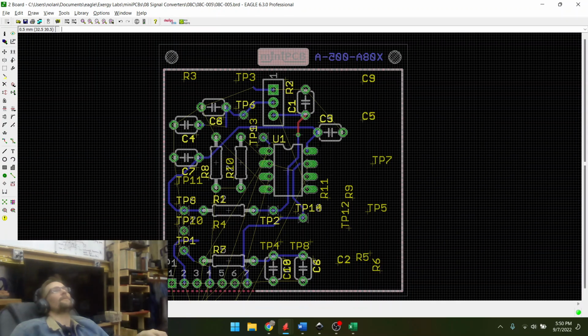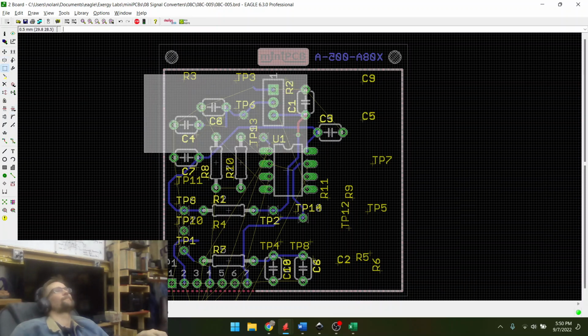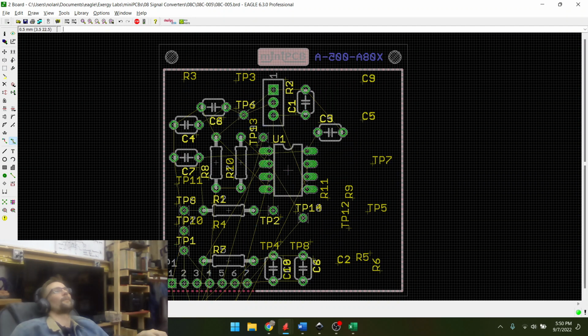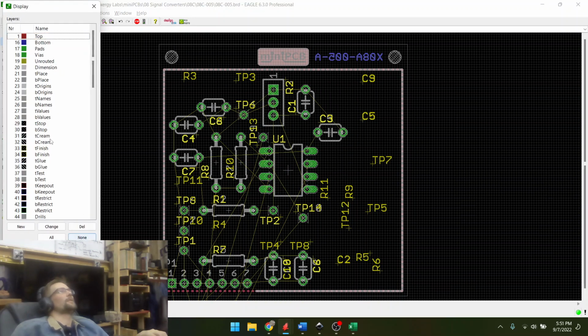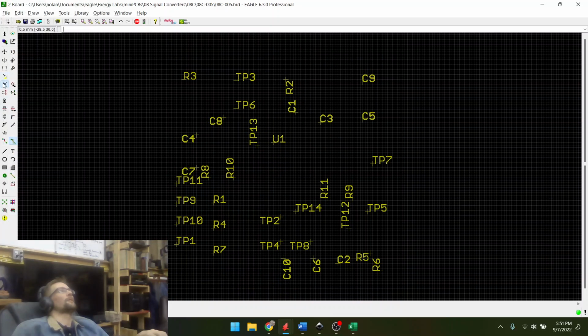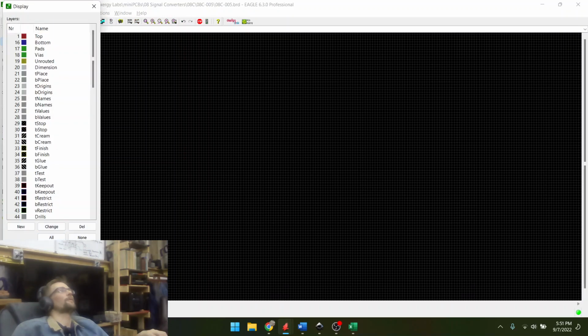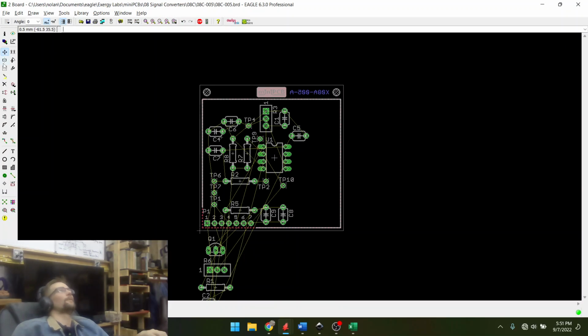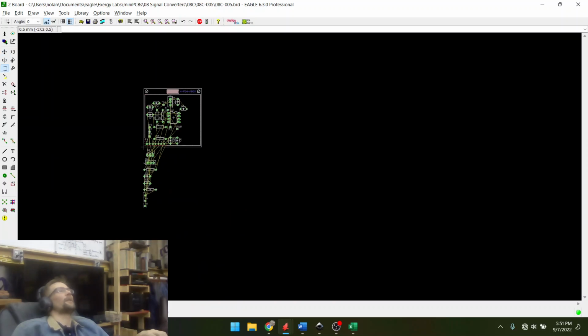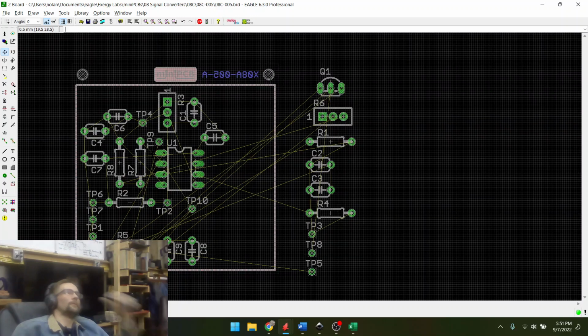These are the parts we need to fit in. This is the layout from the last board that we copied. Rip up group. Say none and show me T names. Boom. Delete group. This group. Delete group. Save. Move. Show all. Apply. Okay. Grab these guys. Drag them up so they're kind of next to it, not underneath of it, so I can place them a little easier.